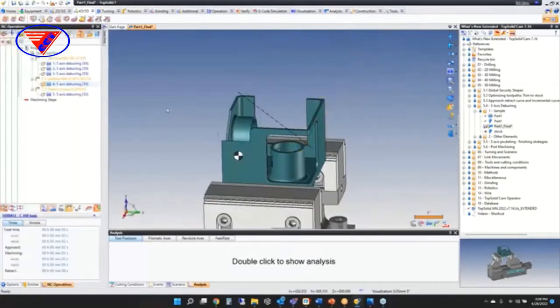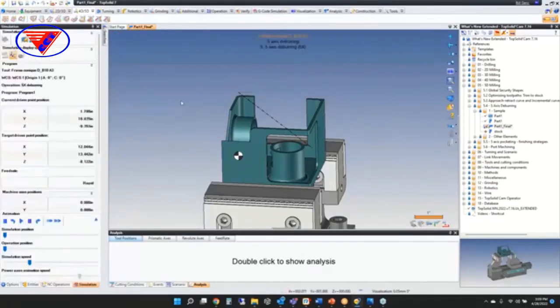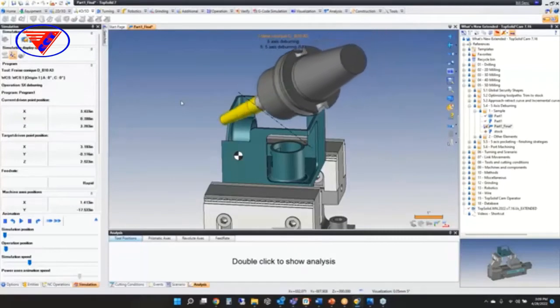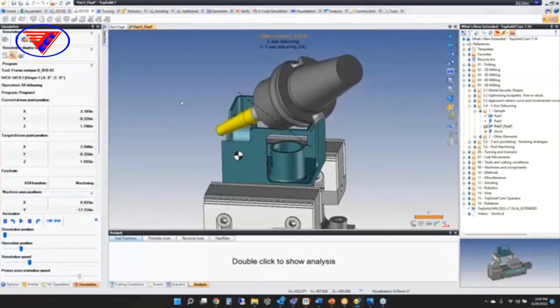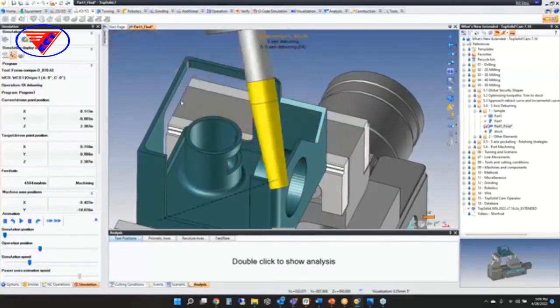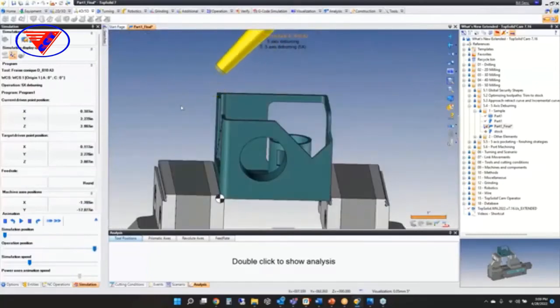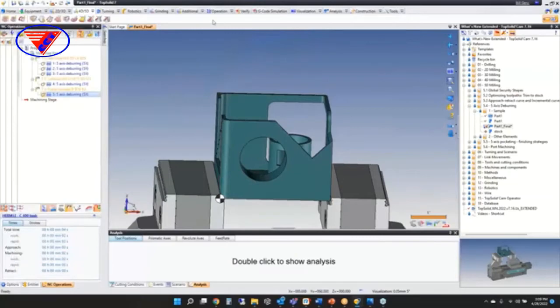And so on. And then lastly, you don't have to use a ball end mill or chamfer mill. You can use any old end mill. So for example, in this one, I'm using a tapered end mill. Let's let this thing come in here. And we're going to use the side of the cutter to add the chamfer. And when I say the side of the cutter, I mean the side of the cutter. Nice and easy.